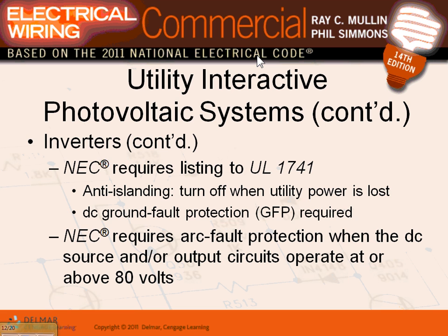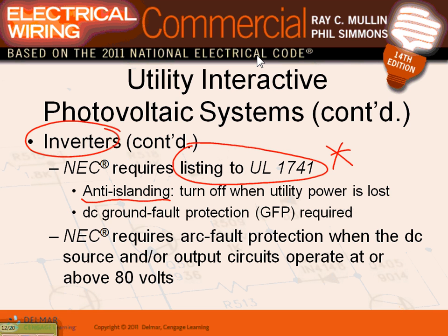Inverter. If you have a utility interactive inverter, guys, back to my inverter, it has to adhere to a rule under UL 1741. Very simple rule. This rule they call anti-islanding. That inverter has to be able to do a function called anti-islanding. If you're tied to the grid, what happens if a tornado comes in Minnesota and hits the transmission line and you lose power?